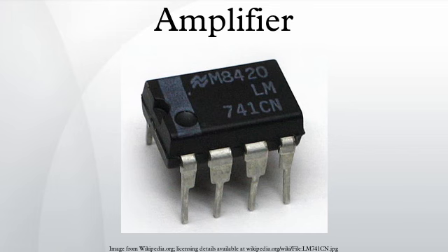Up to the megahertz range, only discrete properties need be considered. For example, a terminal has an input impedance. As soon as any connection within the circuit gets longer than perhaps 1% of the wavelength of the highest specified frequency, design properties radically change. For example, a specified length and width of a PCB trace can be used as a selective or impedance matching entity. Above a few hundred megahertz, it gets difficult to use discrete elements, especially inductors. In most cases, PCB traces of very closely defined shapes are used instead.